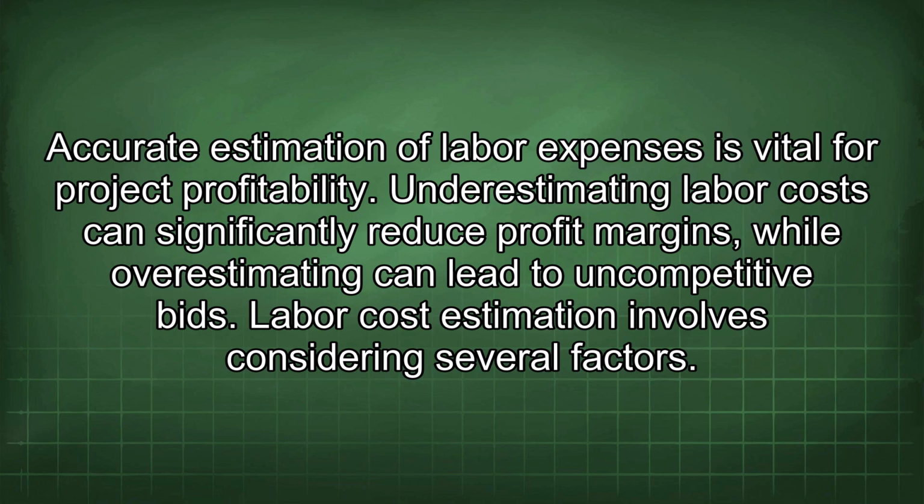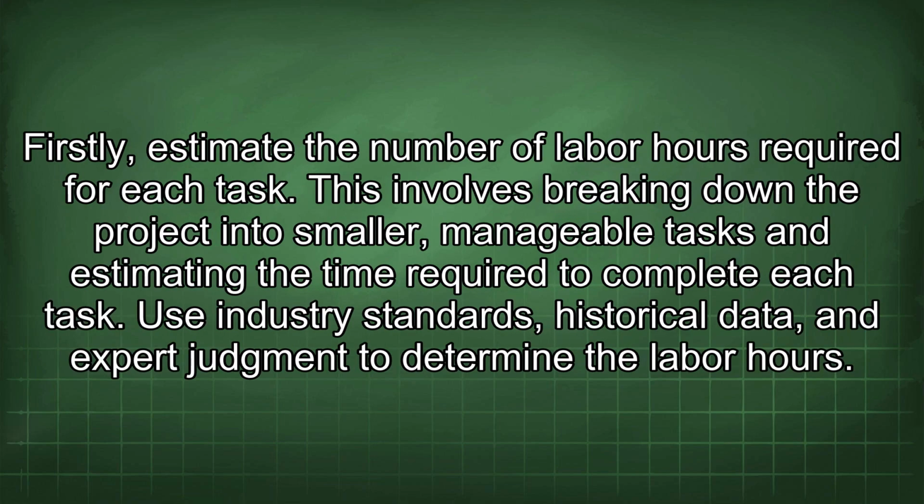Labor cost estimation involves considering several factors. Firstly, estimate the number of labor hours required for each task. This involves breaking down the project into smaller, manageable tasks and estimating the time required to complete each task. Use industry standards, historical data, and expert judgment to determine the labor hours.